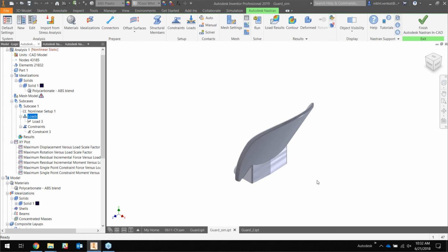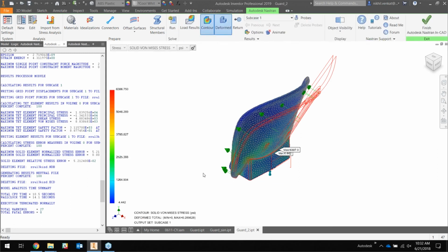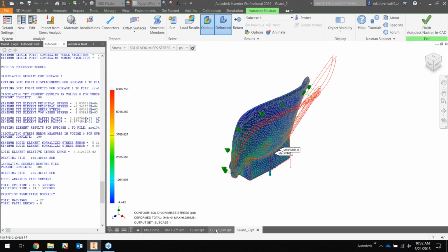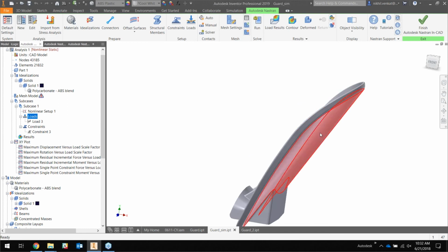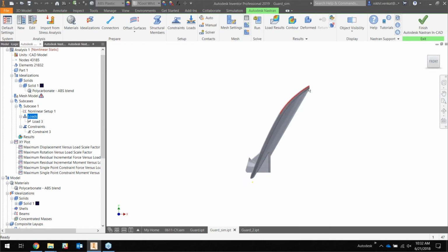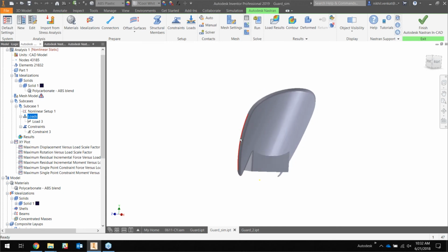Yale is asking why it results with high stress concentration in the middle of the edge. So the reason for that is the bending that we see. It doesn't just bend from here to here. It bends from here to here, and these edges bend inwards. So because they bend inwards, we see stresses on those.